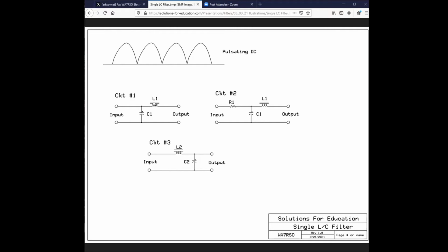But that's not true here. You disconnect this guy here and that field collapses so fast that you may only have 12 volts here, but you can easily develop 12,000 volts coming off of this guy if that magnetic field collapses real fast. After all, that's how the car spark coil works. Collapsing magnetic field. I've got another drawing we can bring up after a while.